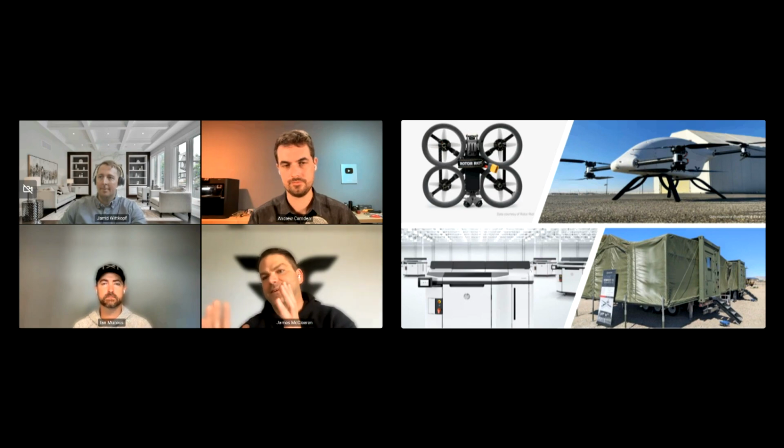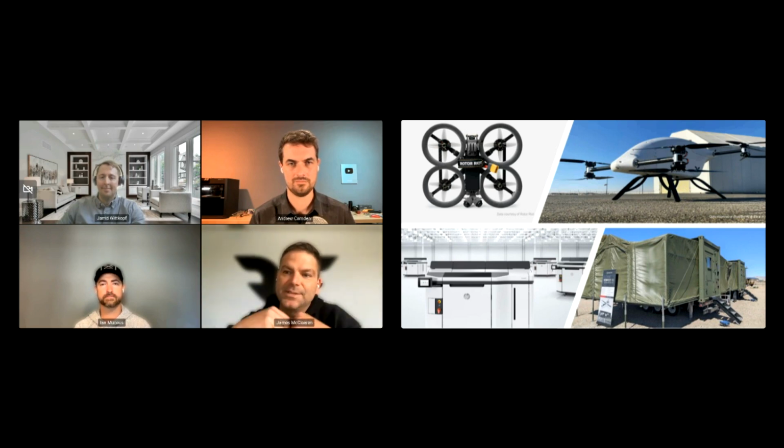Maybe it was like 500 parts, big parts, where it made sense to make a metal tool, but maybe now you can make MJF tools or soft tools. Maybe it's 1,000. I think that's a big enabler that people should think about MJF for, is making tools. We cast all of our own lenses in-house, so anything clear, we cast them, and we print our tools and everything we need for that out of MJF, versus traditional methods. So I think it's important to say that, we've been focused on end pieces, but it's also interesting to think about the time horizon, that MJF could make tools as well.